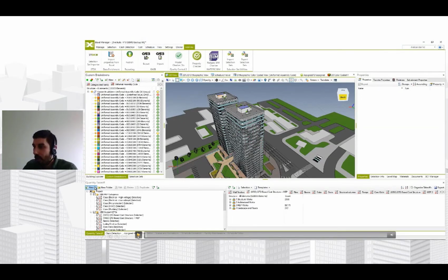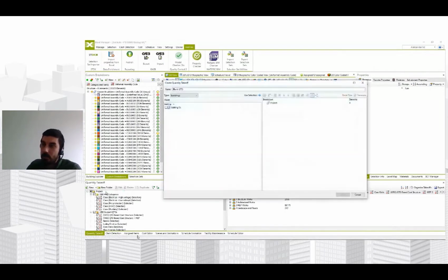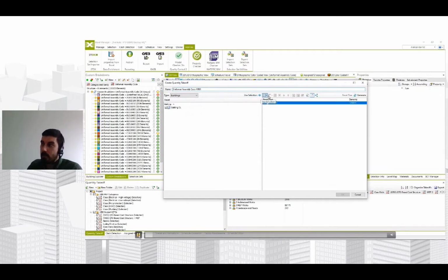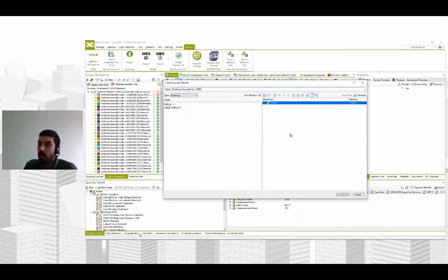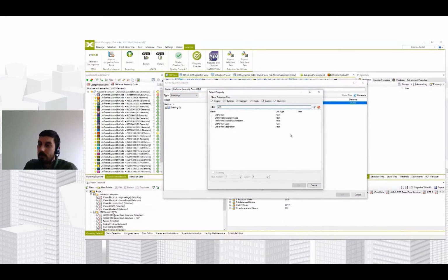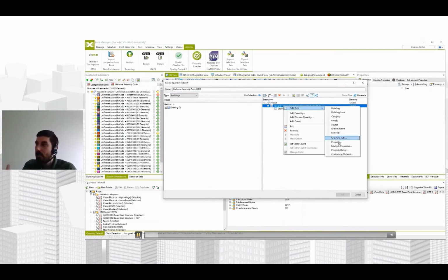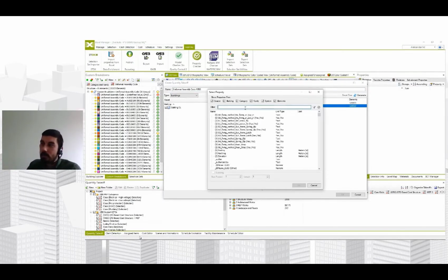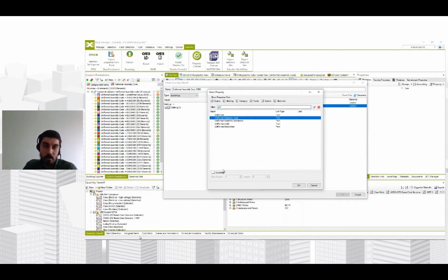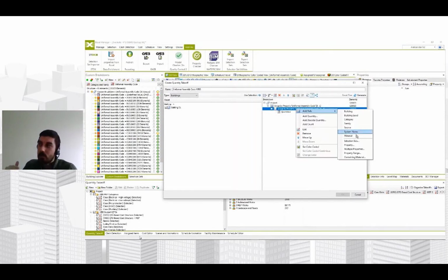So we have this information populated in the model, and based on it, we're creating a work breakdown structure. How can we do this? By using some simple functionalities of Excel Manager, where we can sort model elements by this code that we have added. On the first level, we're going to use just the first symbol of this coding system because it's Uniformat, so it's going to be A, B, C, D, E, F. These are the main groups of works.